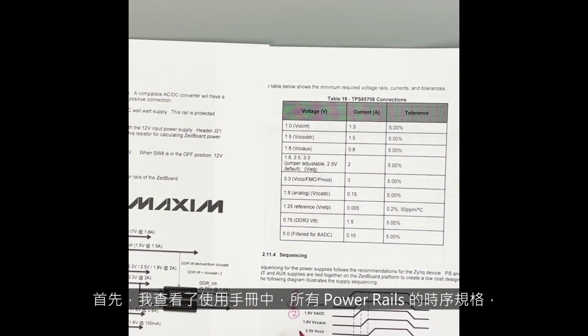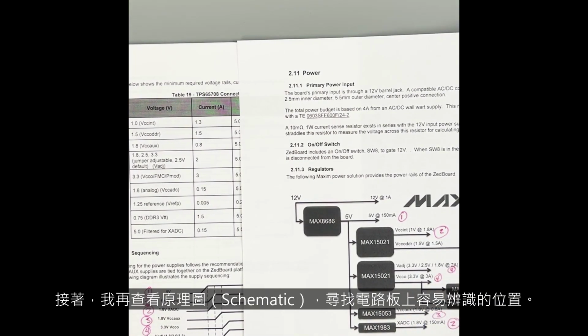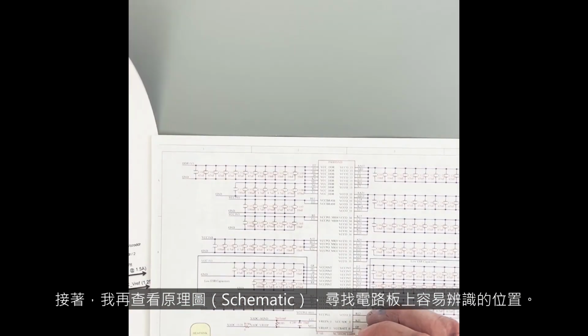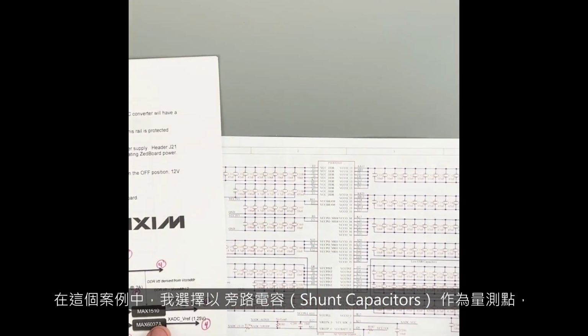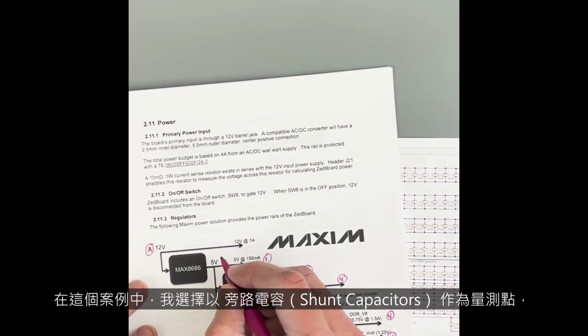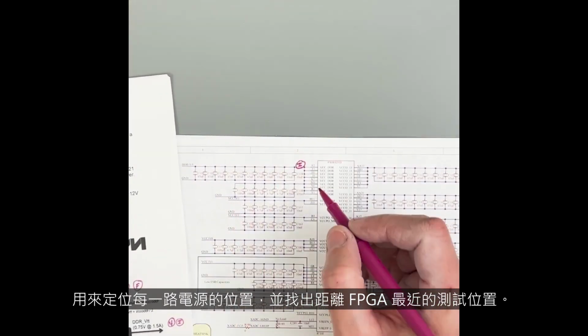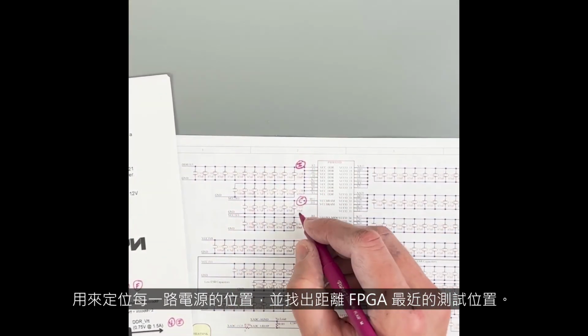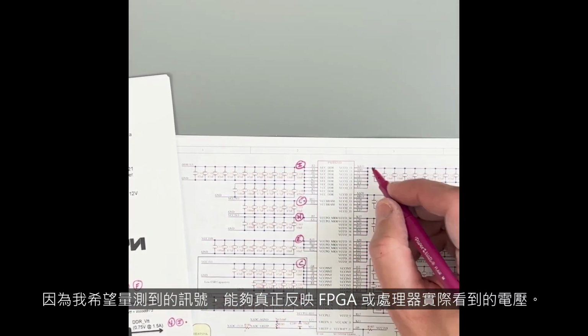Now first I found the user manual, I looked at the sequences of all of the power rails, identified where they would be, which chips were actually providing them, and then went to the schematic. I was looking for identifiable locations on the circuit board, in this case it was shunt capacitors, in order to locate where these power rails were and find a place very close to the FPGA where I could measure them, because I wanted my signal to represent what the actual processor or the FPGA was seeing.